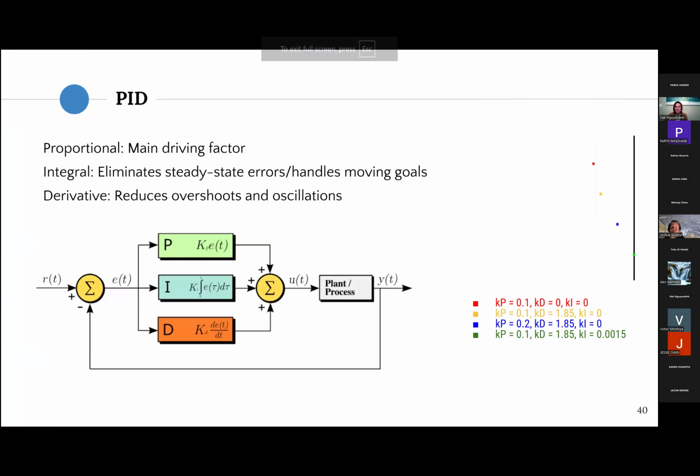So this is in reference to the micromouse slides, but if you have taken PID or done micromouse or dealt with control systems at all, you've probably heard of PID. That is a proportional integral derivative controller, and it helps us track certain things. So say I'm a car trying to catch up to some specific point. The farther away I am from it, we can call that our error term.